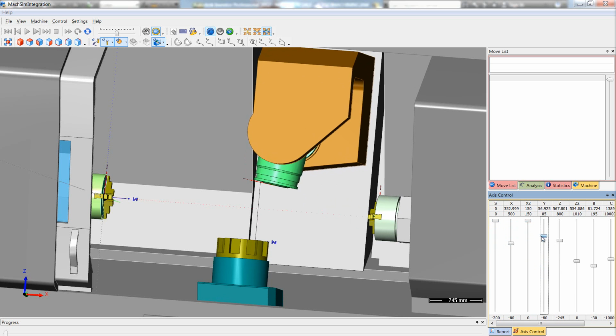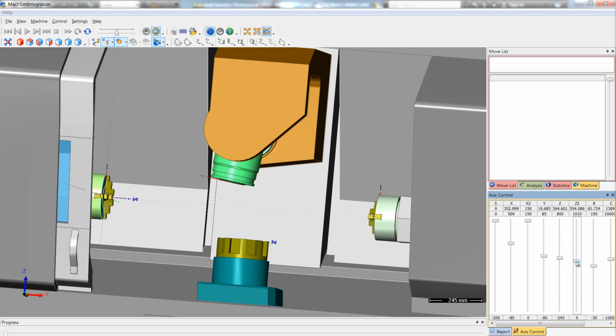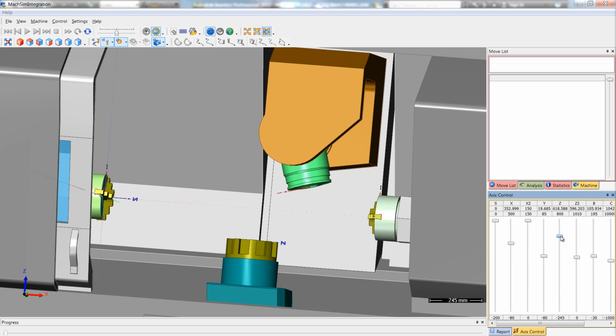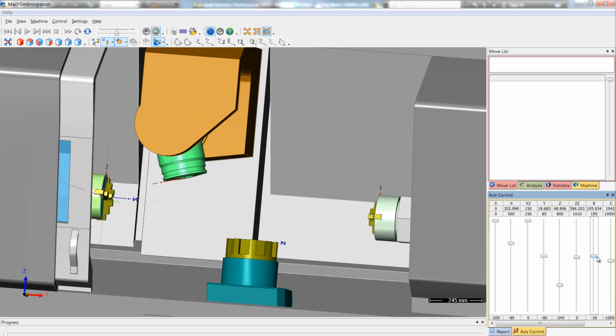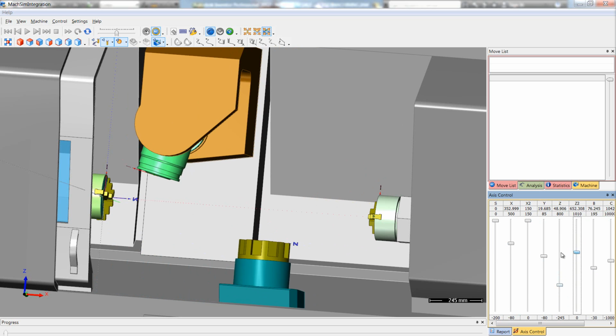We also have the main spindle as it can move also in the Y direction and moving obviously in the Z direction as well. The bottom turret here shown moving in the Z direction. We also have the direction of the turret as shown over here, complete control, and of course we have the spin of the main turret. Now we can have all the different combinations that I've mentioned before. We can have the main turret working with the back spindle or the front spindle as shown over here. And we can also have the bottom turret working with the different spindles as well.